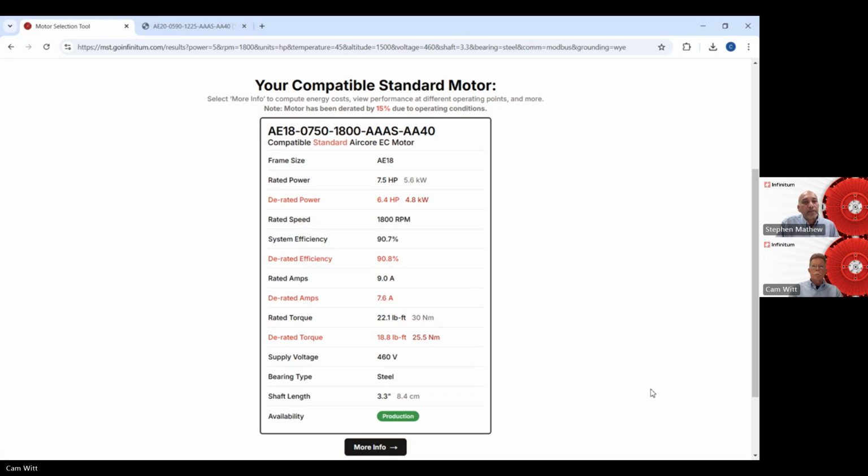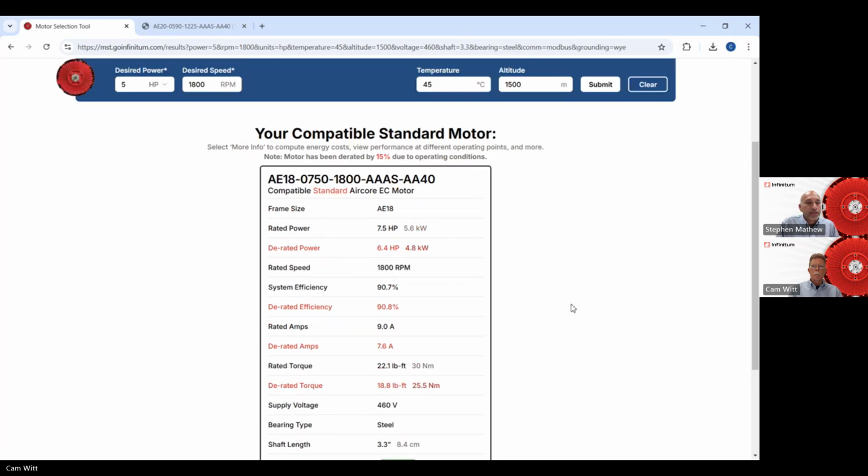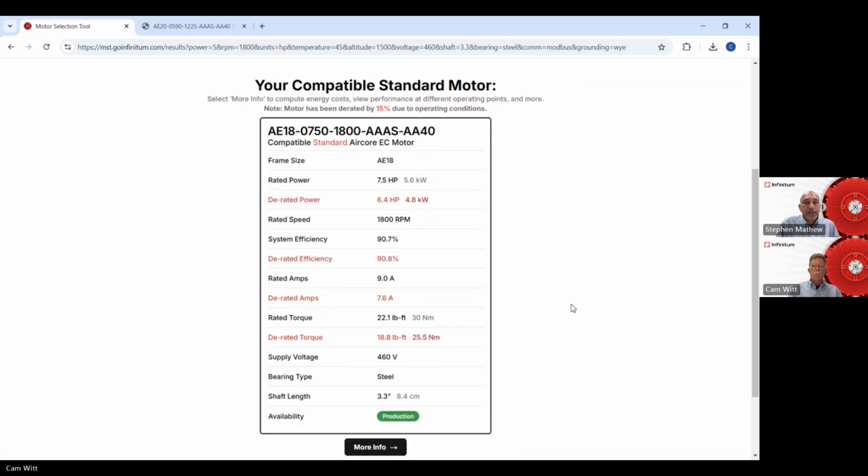Related to that, I think it might be important for our audience to understand the PCB stator that's used in the Infinitum motor. Actually, it's very unfortunate. We are at 150 degrees C, which is 5 degrees lower than a class F. So it's unfortunate the certification agencies put us in the insulation class B bracket, although the material that we use is fairly close to a class F bracket.